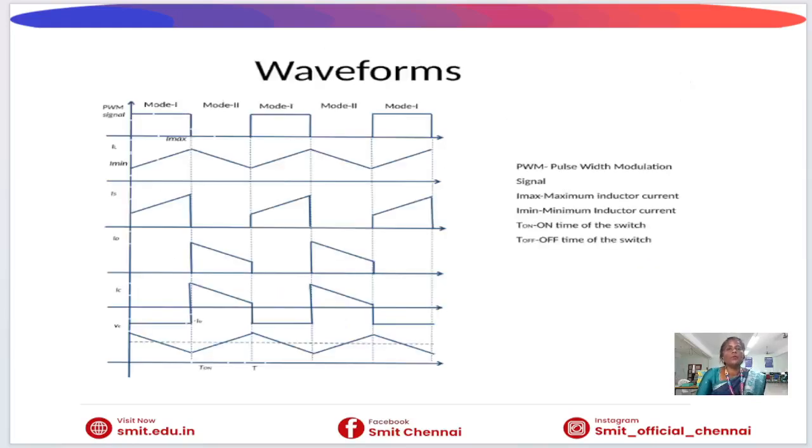This slide shows the important waveforms of the buck boost converter. The first waveform is the PWM gate pulse controlling the switch. The inductor current increases during the on period because energy is being stored. During the off period, the inductor current decreases as energy is delivered to the load. The voltage across the switch and the output voltage also vary according to the switching action. These waveforms help us understand the converter operation and energy transfer process.